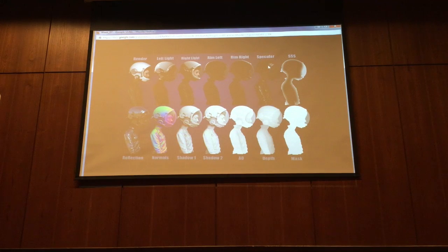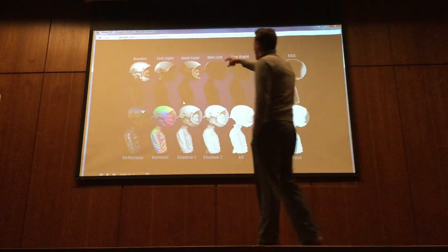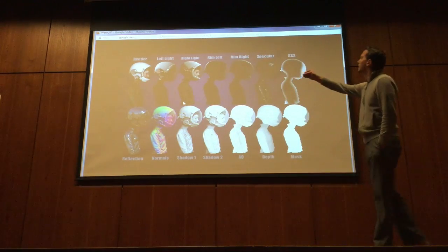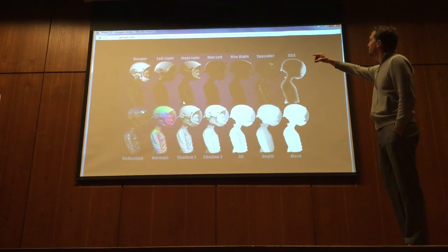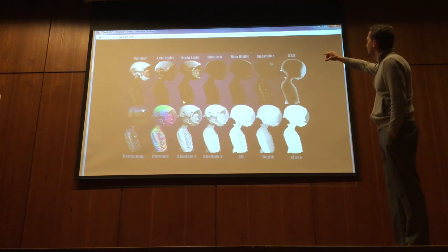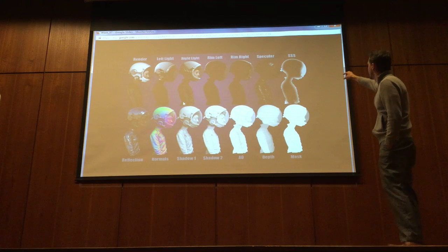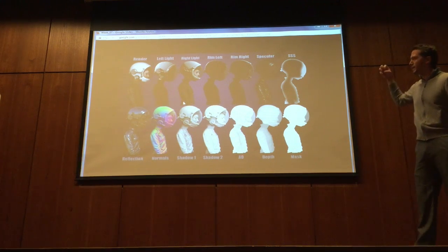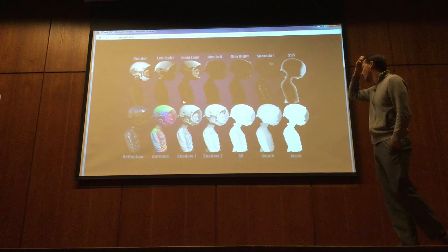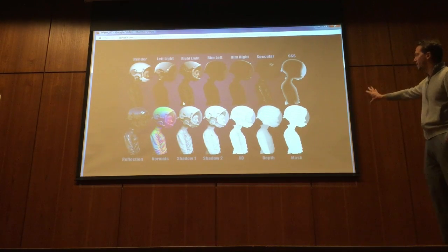So yeah, this is an example of all the different passes. If we look at this, the image on the left is typically what we think about when we think about a render, right? That's the diffuse color. It's everything combined. But here, this person has layers of light. They've got a left light, a right light, rim lighting, rim light left, rim light right, specular. The SSS is subsurface scattering, right? That's light coming through the material. Then they've got reflection, normals, which could be useful. All the different shadows, ambient occlusion, depth, and maybe a mask.